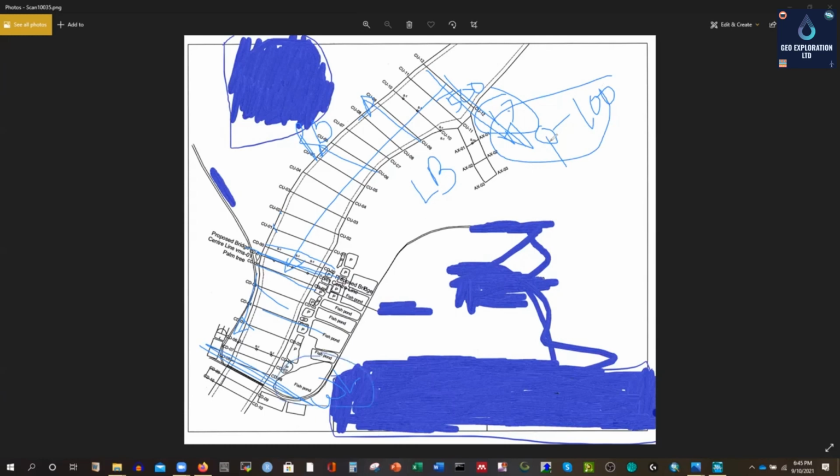Then if we use that, that means we are designing the bridge for a 100-year return period. If there is a flood that has a return period of 100 years, then the bridge has to survive, right? The bridge will survive for this type of flood or rainfall event or flooding event, whatever it is. So that is the condition. We have to be able to calculate this one. So these are the input data.